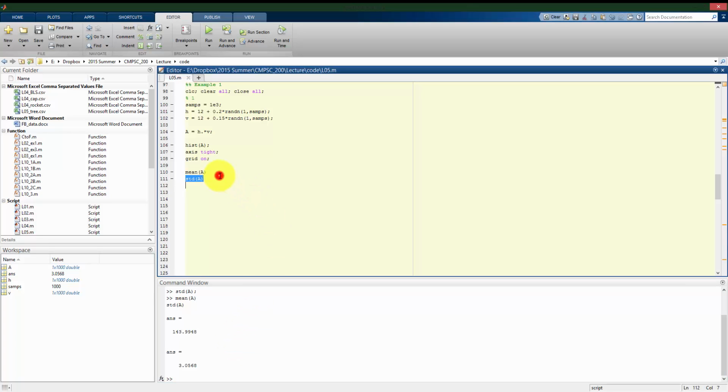This is what I would call the tolerance, or I could express the tolerance as a standard deviation. If this is how our tiles are cut, with this sort of distribution, then we can expect that if we measured the areas of all of our tiles, it would be 144 square inches plus or minus 3.06 square inches, where that's the standard deviation.